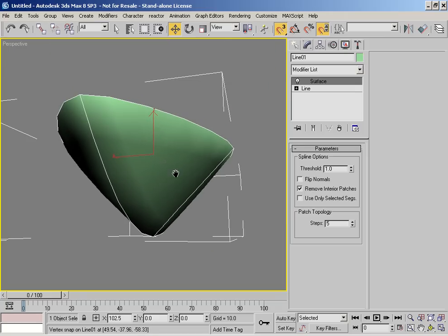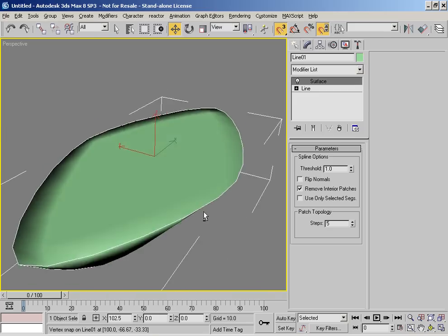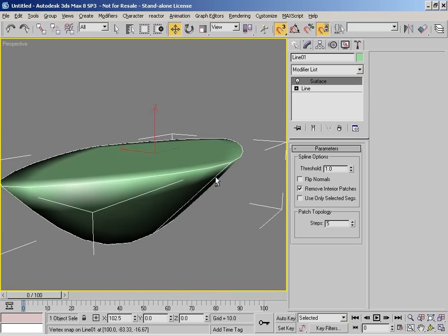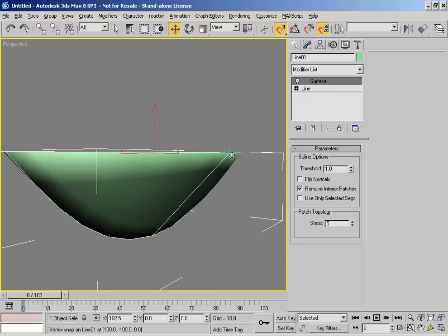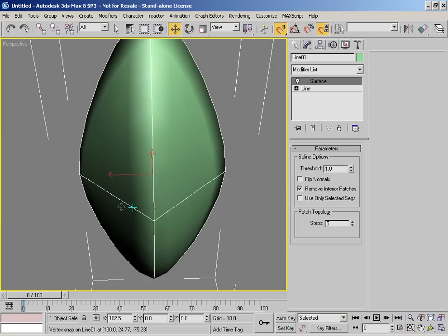Now the way Surface Tools constructs the surface geometry is by using threshold values, the distance between your vertices. It's obviously good to have the vertices in exactly the same point, hence using vertex snap, but the vertices don't need to be welded together, they just need to be within this threshold level, hence having 2 additional splines which are branching off from the midpoint on this one spline.